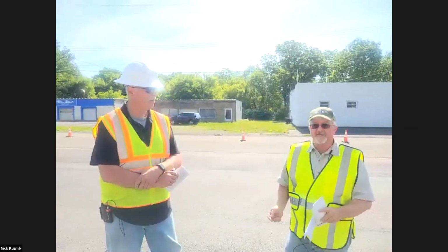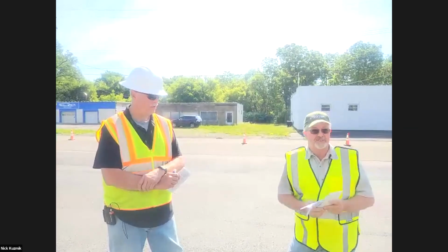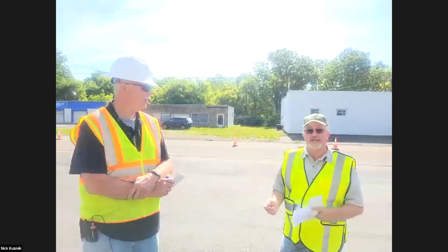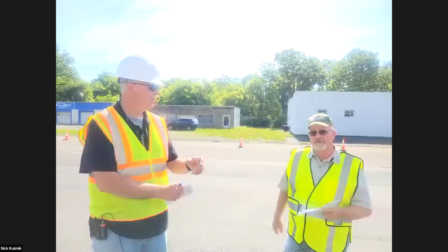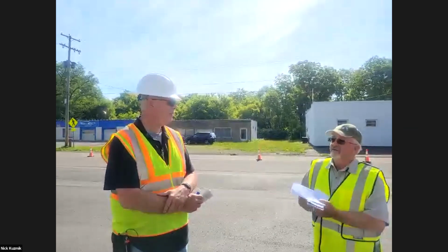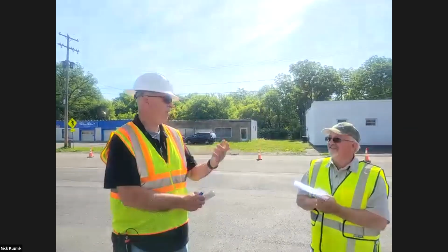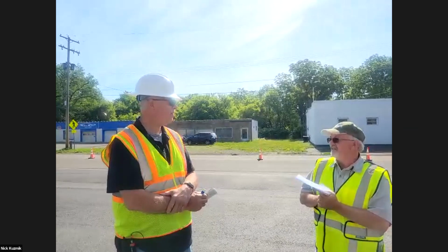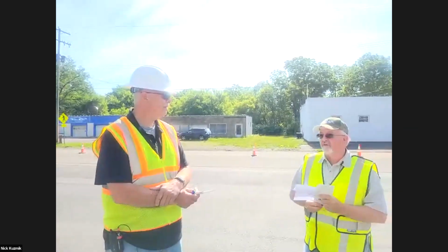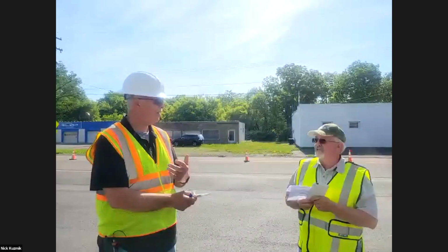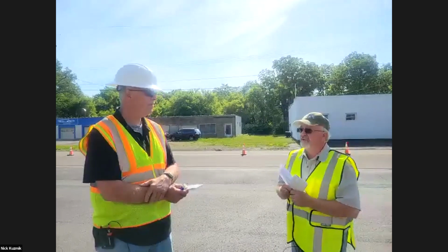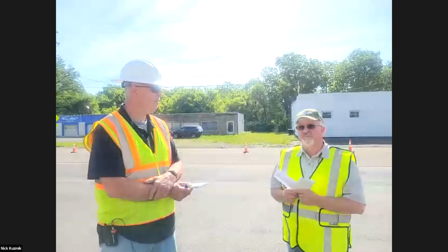And then you want to know if you have the right signage. Again, 3 signs ahead, one telling that there's going to be work coming up, one that says what's going to happen, and then another one telling you there's going to be a flag. Which brings up a good question. What happens if I don't have that sign? Say I'm missing one of the signs. I got 2 or 3 of them and I don't have one. You should, well, ultimately you should get one. Get the signs, but if you don't have it at that job, maybe reach out to some of your neighbors, local jurisdictions, maybe your neighboring town.